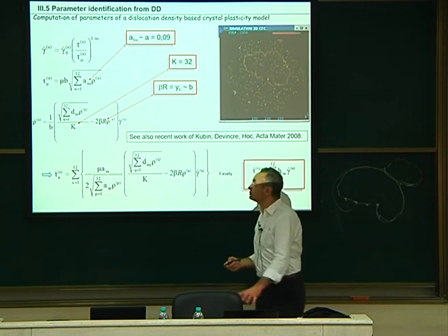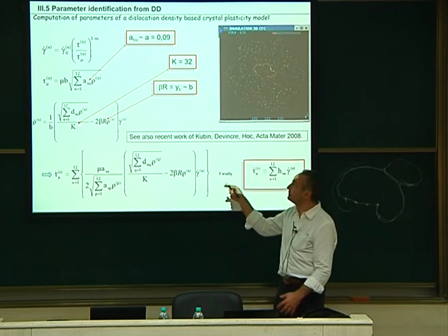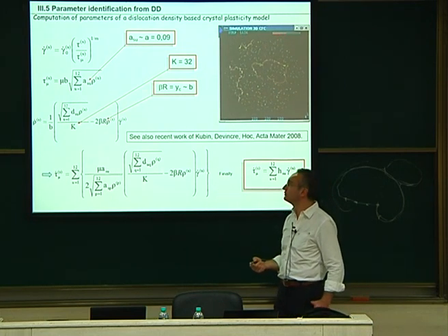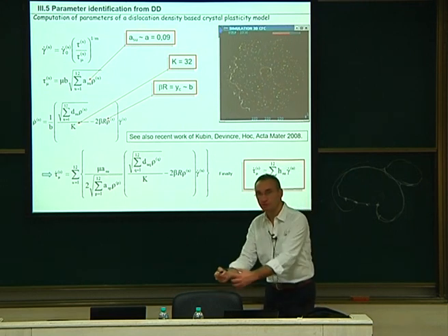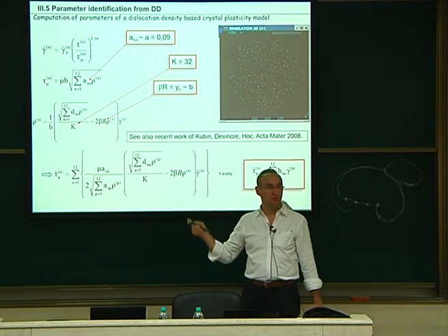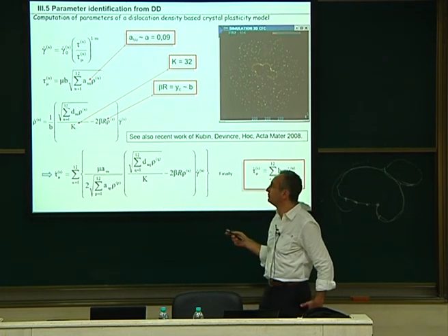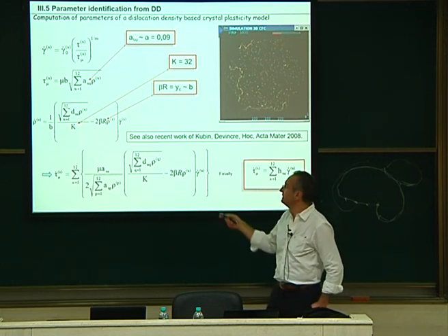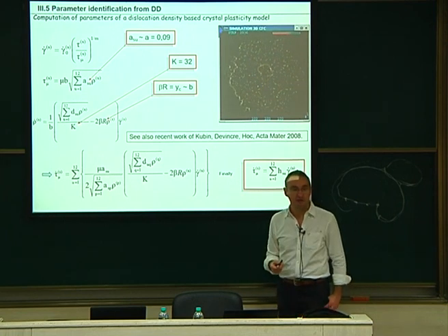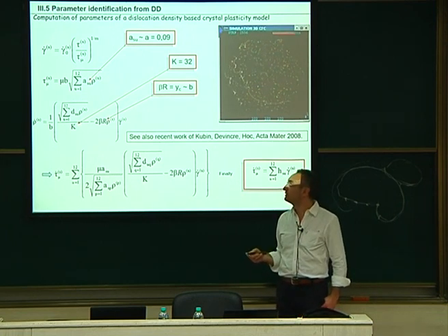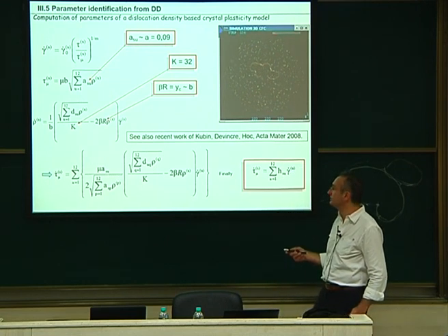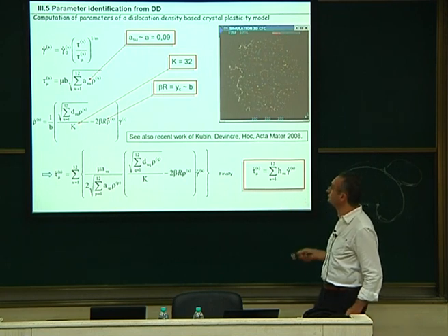Okay. So in conclusion, if you're interested in crystal plasticity modeling, you can use such a set of equations. I think they are very good equations. You can even be closer to the theory, to the experiments, by changing this expression a little using what they propose. I'll let you read the paper if you want. I have it here, by the way, if people want it. And you can change this equation to have it closer to the experiments. But this is what I think is a good way to tackle continuum scale modeling using dislocation density based equations. Okay, so have a look at that paper.